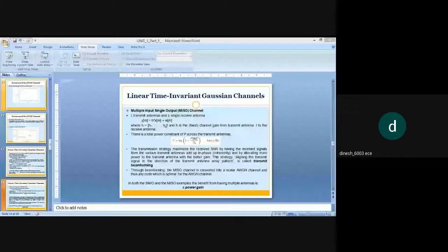So what is this water filling scheme? This water filling scheme is an optimal power allocation system where a water filling methodology is used with respect to time, where data rate and power are increased when the channel conditions are favorable and they are decreased when channel conditions are not favorable. If this channel is giving good efficiency, then we can increase the data rate and power.